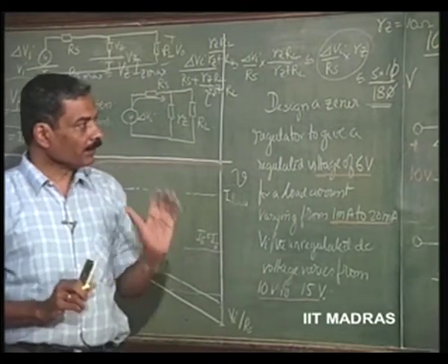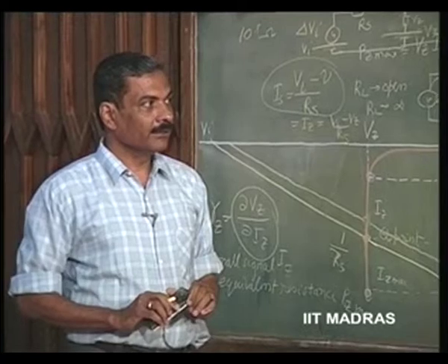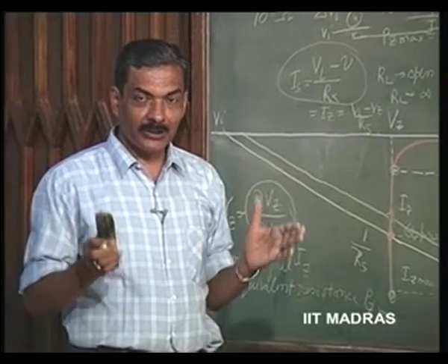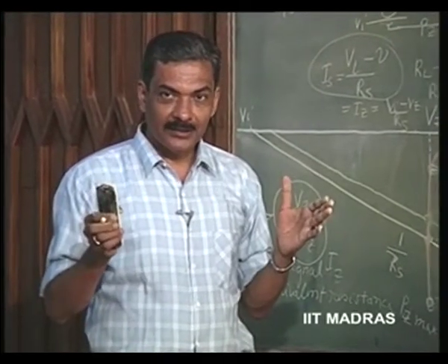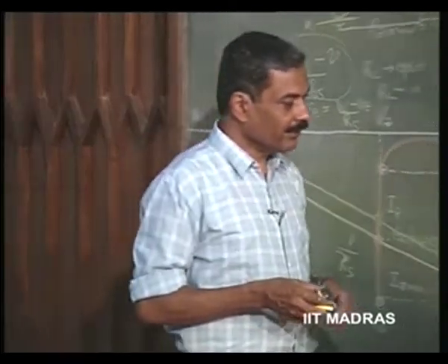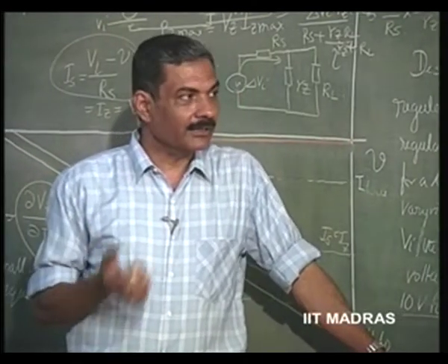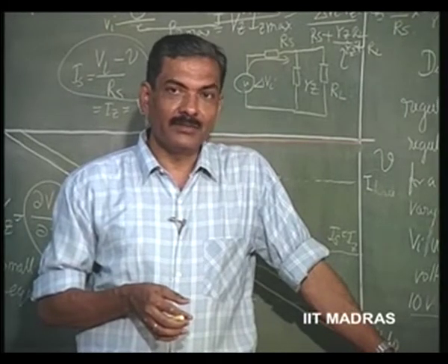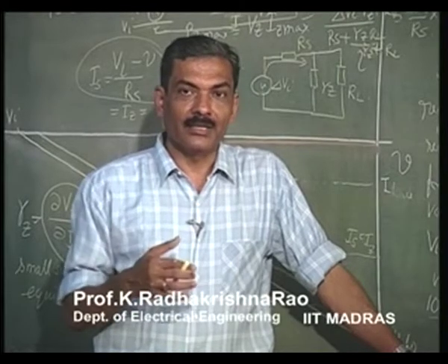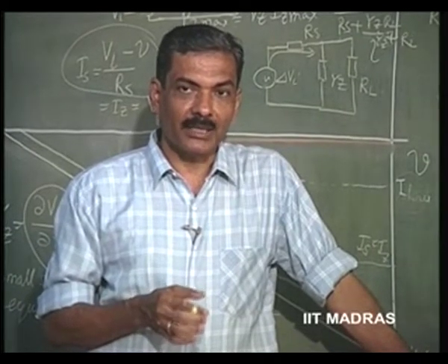So, this kind of problem we can discuss whenever we are confronted with obtaining an absolutely invariant DC, when AC is varying. Such Zener regulators are quite common as secondary power sources, wherein such regulation is very important, so that the operating point is known to the designer beforehand, and therefore, he need not be worried about the variation that is occurring in the power supply.